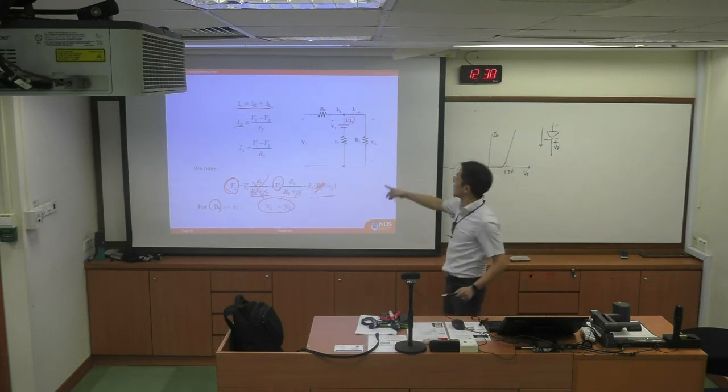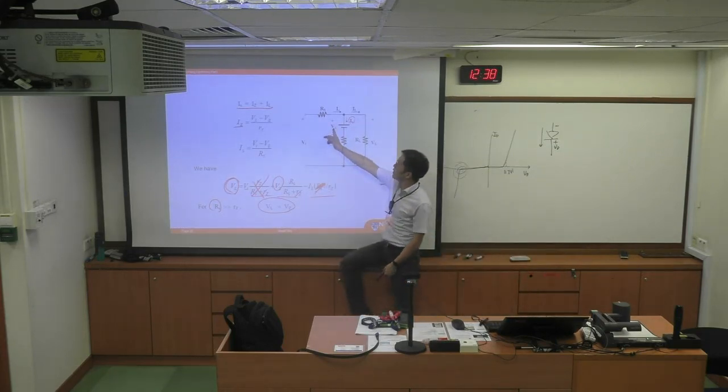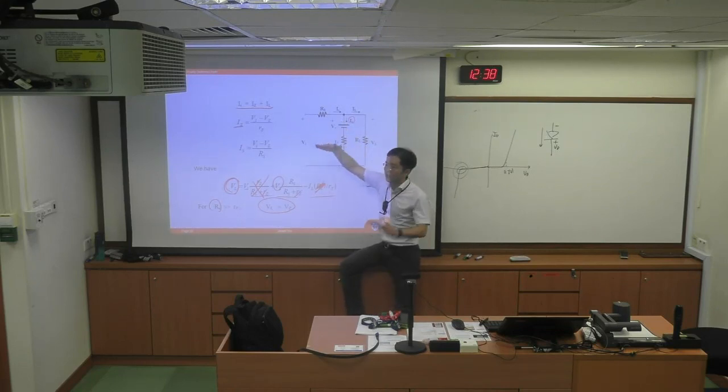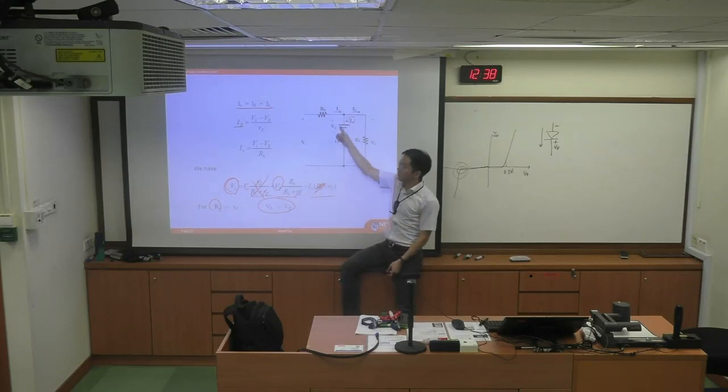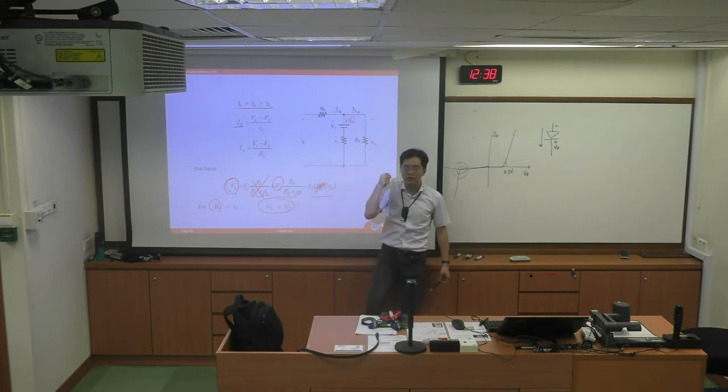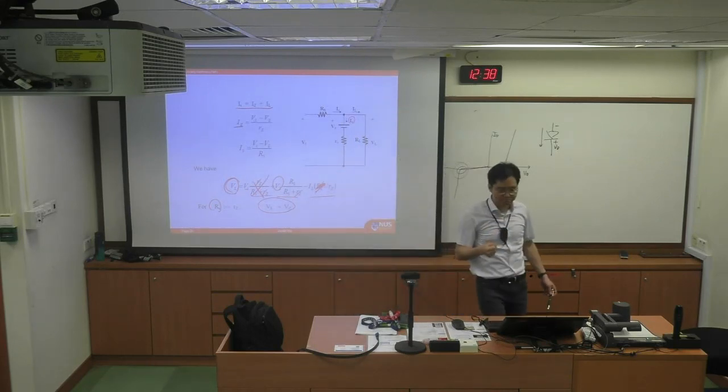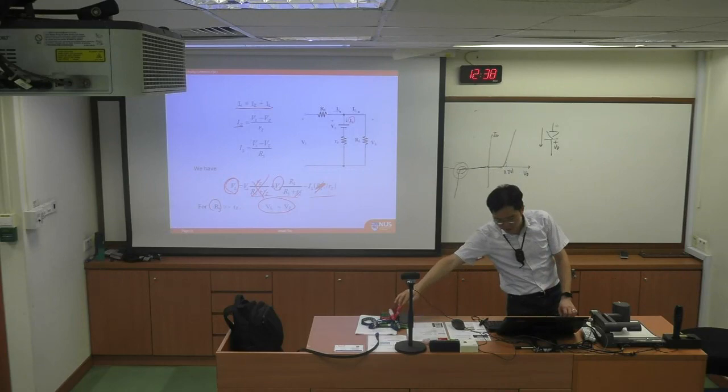So if the Zener diode voltage was, let's say, minus 10 volt, and you go in reverse bias like this, then even with the fluctuation in the input, your output will be almost always 10 volt and stays at 10 volt. Right? So then where does the ripple go? The ripple is going to be flowing as a reverse current in the Zener diode. So in other words, the Zener diode will be absorbing those ripples. That's what the shunt regulator does.